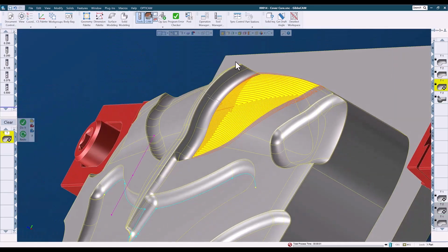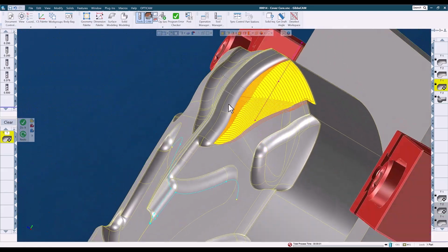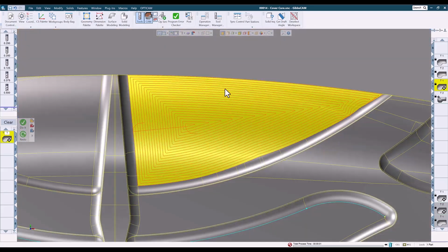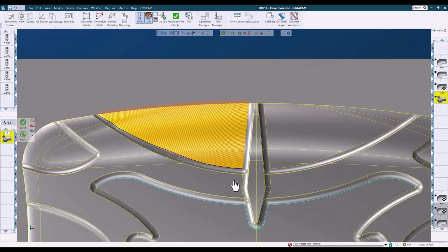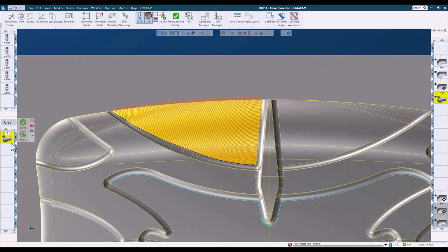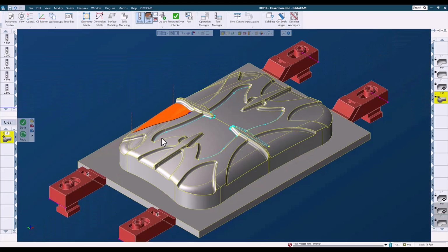On this toolpath, we're using the Advanced 3D Constant Step Over pattern. This toolpath is created by offsetting the boundary of the cut in a constant offset and maintaining the ridge height regardless of the surface angles. This last one is from the multi-axis process, and the pattern is parallel to curve or curves. This toolpath allows us to select one or more faces that we want to machine and curves that the toolpath will then run parallel to.